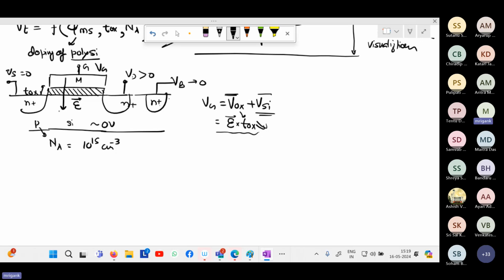Now, when you apply a positive potential, the holes are supposed to be pushed down. They will be pushed away, right? So all the holes will come down, and the minority electrons will be accumulating near the channel. And as a result, the channel formation takes place. In simple way, this is the mechanism. That's why we need a positive electric field. That's why for NMOS, we need to apply a positive gate potential, which will conditionally create the channel by pulling the electrons close to the surface.